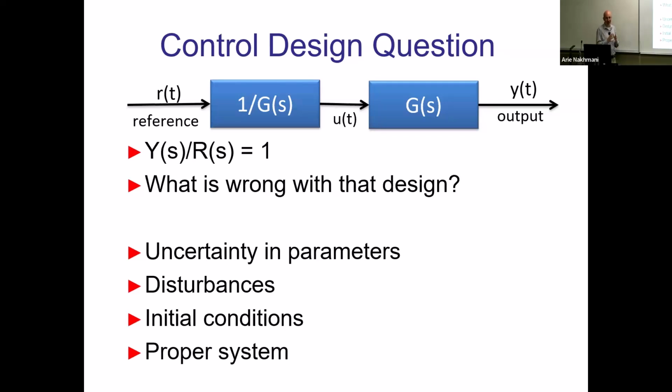You actually can realize them because they are causal, which means their future depends only on past and present. They compute the signal right now based on all of the past signals. The inverse system, which might be the opposite of that, might not be proper at all, right, and needs future values to compute the output.